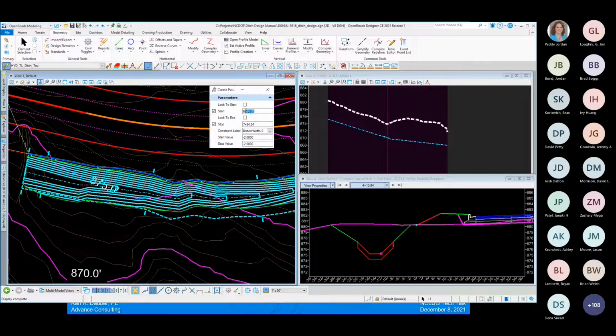And that's going to be 660 to 680. Now, the reason I picked those stations, it's explained in the new guidance document on the website: a 5-to-1 transition ratio is being recommended for these transitions. So for a 4-foot expansion from 4 feet to 8 feet, that's going to occur entirely on one side of the ditch.